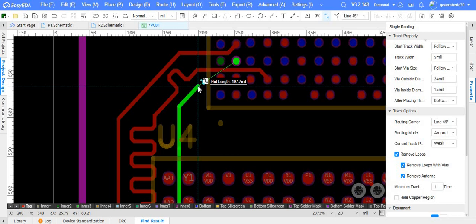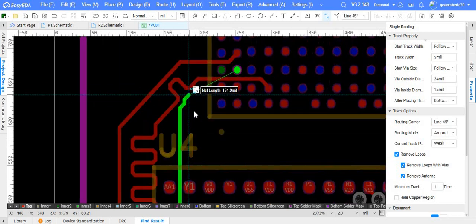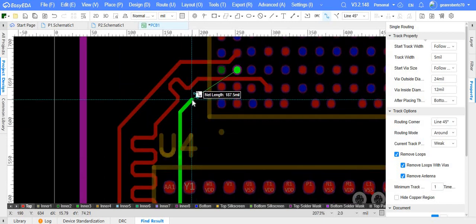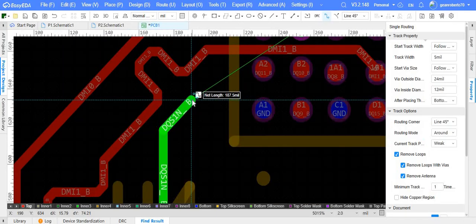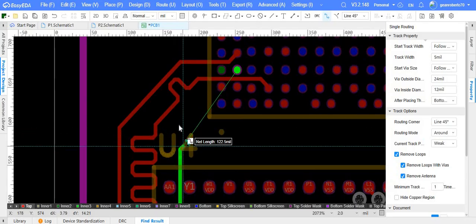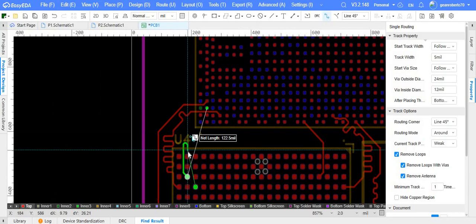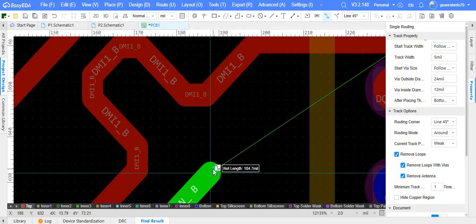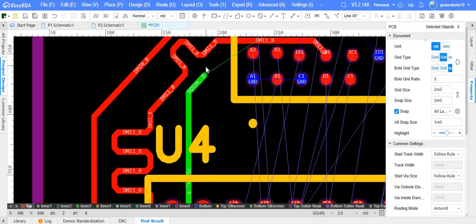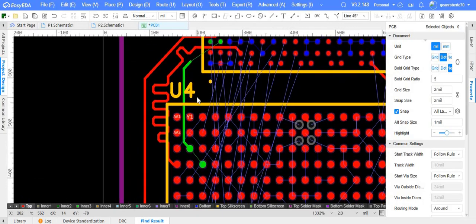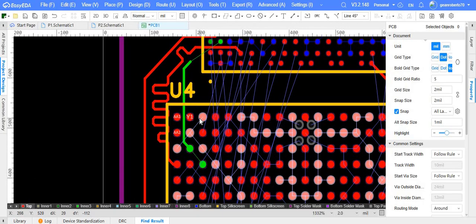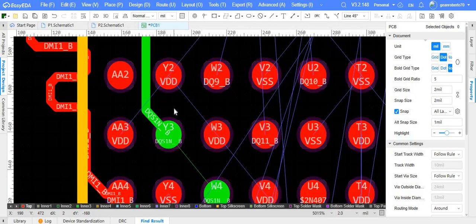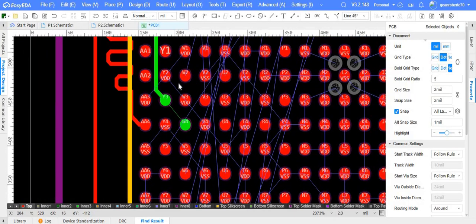And remember that I said that when routing we need to pay attention to not blocking out the path of the traces. So this is why we need to follow an order to do this routing. We need to do first the outsiders and last the insiders.